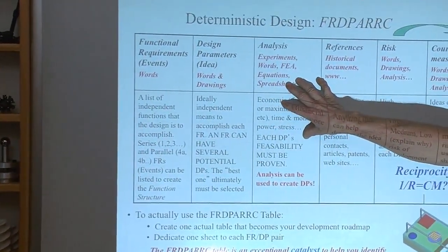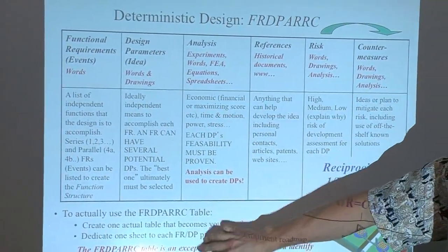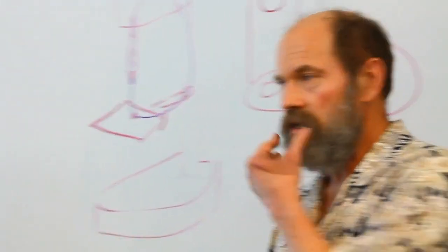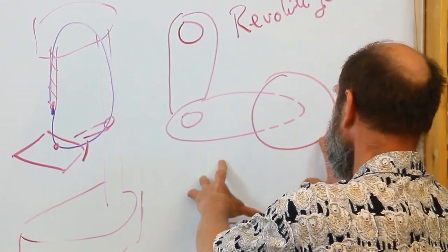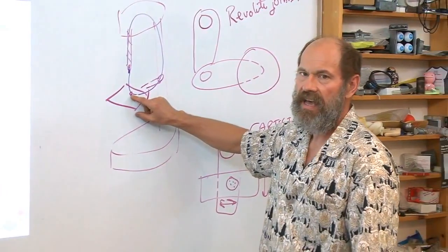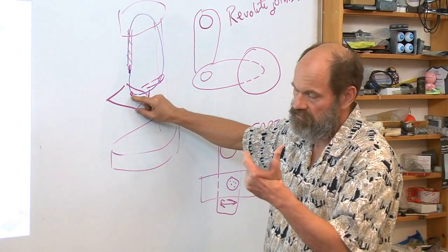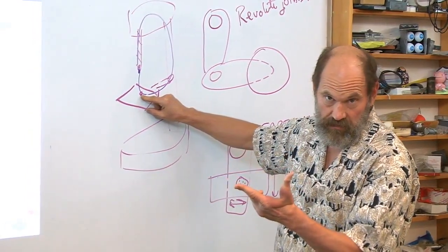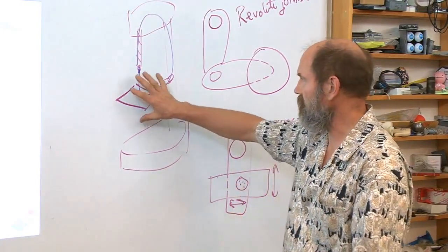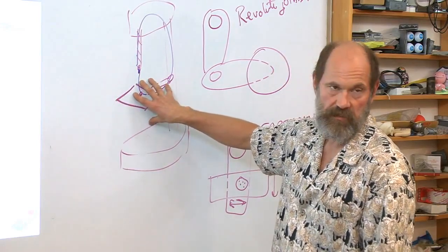And why are you thinking, oh my God, physics, analysis, equations? This is where you really make your mark. Because as you're thinking early on, you start doing the analysis of, wow, I've got to move this to move the part on the drill, but how? And there's three types of things. Accuracy, and then you've got repeatability or precision, same thing, and then resolution. Accuracy is if this thing was controlled, how well can you make it go to the position you want? Repeatability would be how well it comes back.